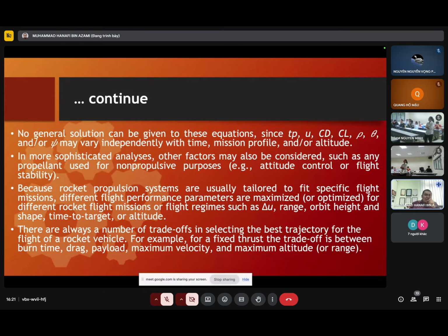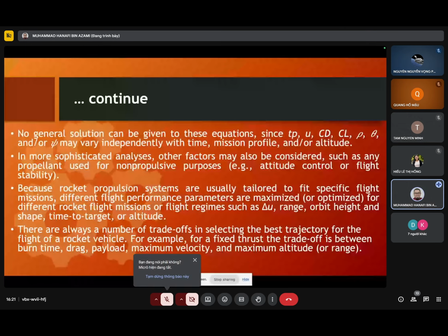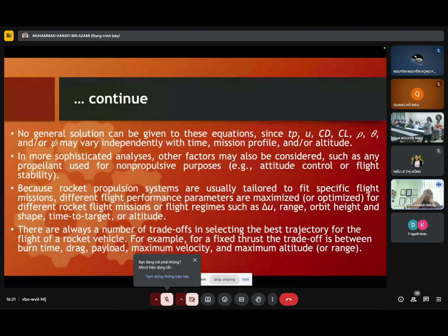But if you go to, for example, a 75-degree angle, having a MECO velocity of a certain value and weight of a certain value, your rocket doesn't go far. With a higher angle, 75 degrees, it doesn't go far, it goes high.